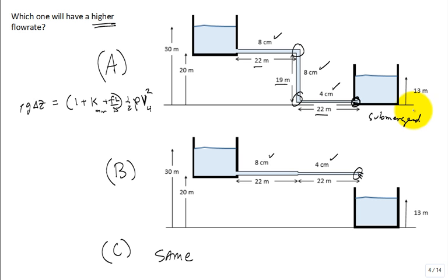But what drives this flow? Oh, these reduce the flow rate. The friction reduces the flow rate, true? But what drives the flow, makes it happen? That elevation difference, right? So let's do this. We start here. We're going to do modified Bernoulli. That's where you end. Let me ask this question. The walls of the pipe, the tank, go up here, and the fluid level goes up to here for that tank.